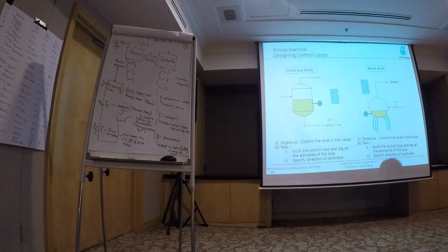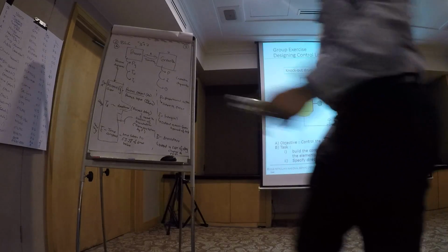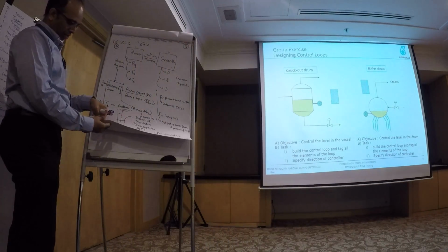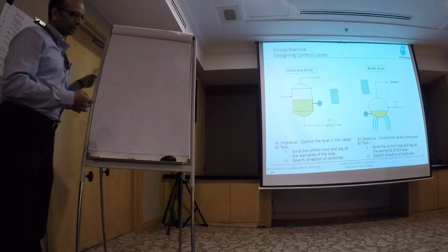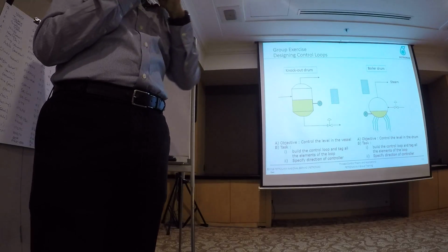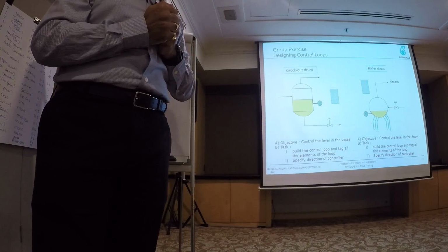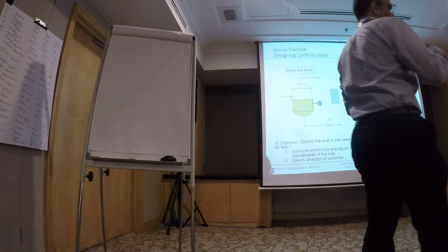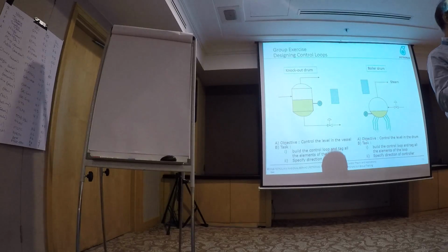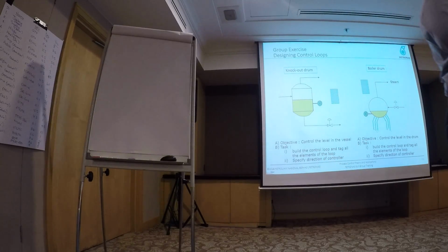What is implemented in a DCS is, if you think about it, if I implemented this equation in DCS, I calculate error now, and I implement it. But DCSs work on a discrete basis, not on an analog basis. That means in DCS we run the controls every second or every 2 seconds. So you go into a control block, and it's like a standard computer, we'll run it at a cycle. In Foxboro, they call it BPC, block processing cycle. So it's how often you run the block.